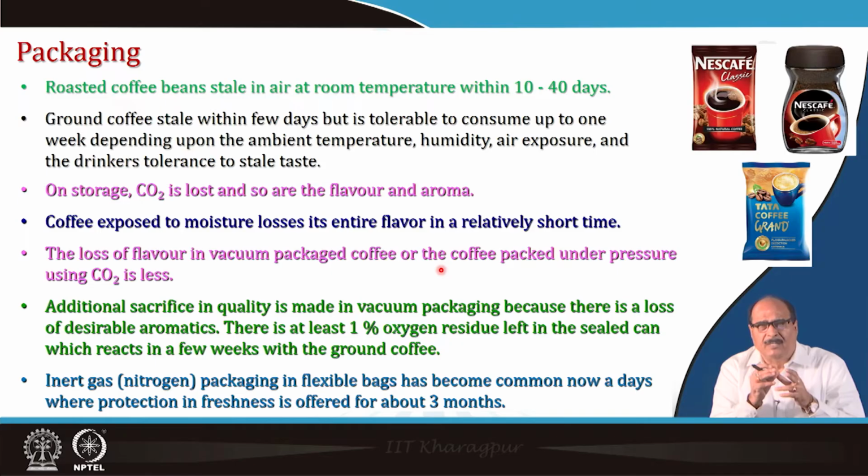And even it has been seen that in vacuum packaging, where a vacuum pump machine is used to create the vacuum, at least about 1% residual oxygen remains in the package. So, even this residual oxygen inside the package is very deleterious, and it creates oxidation and undesirable changes. So, basically nowadays inert gas or nitrogen flushing plus packaging in flexible bags has become more common, which gives protection in freshness up to